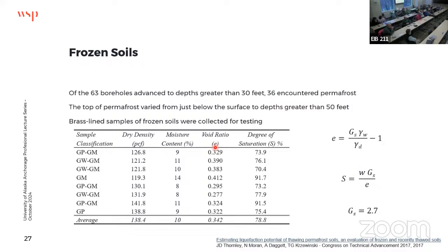Would they be wise to use another soil, another slurry mechanism? Well, if you keep it frozen, let's just assume the thermal siphons work, it's locked in. But say it gets to a point in the future where the thermal siphons are no longer effective because it's too warm outside all the time. So then, would they be wise to use a different slurry than just sand? It's basically just water and sand put in there. They liquefy that slurry when you put it in place. It's vibrated into place with water in it, so it's liquefiable as it goes in, that's how it works. Right, it freezes. Yeah, if it were to thaw, you have a mess.